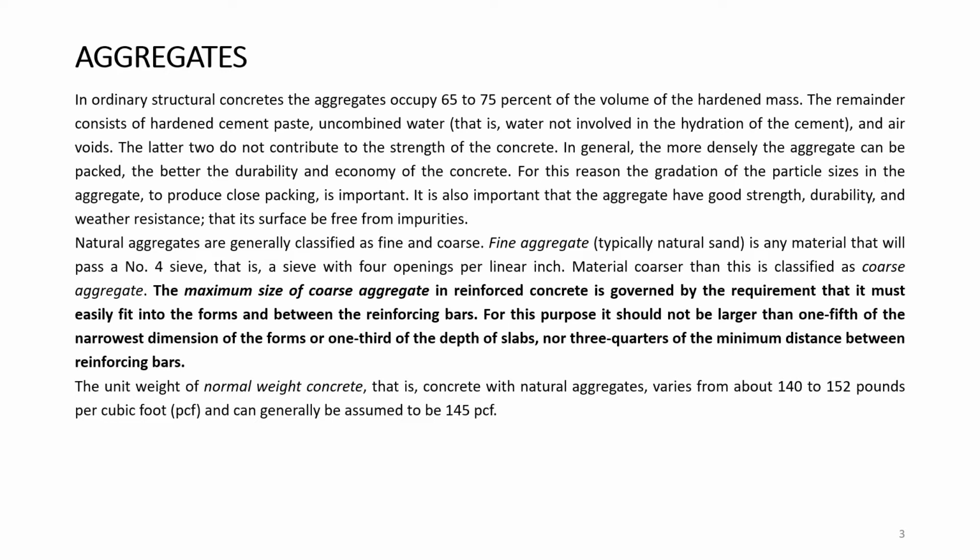And in our country we use another type of aggregate, that is brick aggregate. We crush the overburnt bricks into small sizes and sift according to our necessity, and we use that as coarse aggregate. And sand is the major fine aggregate, available in our country and in most countries.